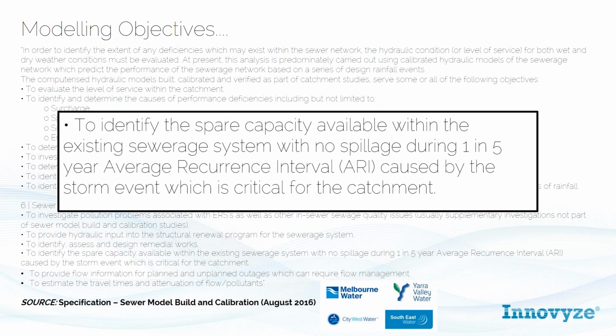And the industry as well is moving towards an effects-based containment standard. A risk-based standard is about a qualitative assessment of risk. An effects-based standard would be a more quantitative assessment of risk. So that's quite an intensive thing to do, not particularly appropriate for all projects. There's a lot of work involved. Receiving waterway models are required. You need to have sediment transport and pollutant transport active in your models to do that. But certainly for high sensitivity catchments and high expenditure type projects, they're really useful. And I know Queensland Urban Utilities are currently working on a project in that space and getting some really good outcomes.